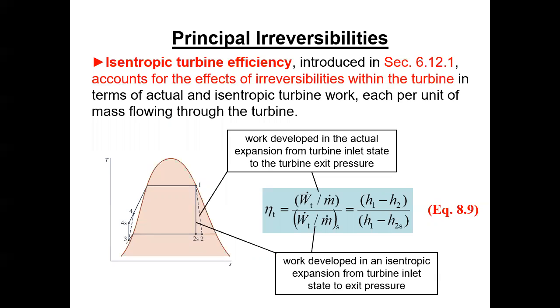That's what typically happens. This isentropic efficiency might be given to you as 70%. So then you calculate the H1 and the H2s, set this expression equal to 0.7, and solve for H2, and that tells you your exit enthalpy. That's kind of the standard problem. Of course, there are always different ways to twist it; these guys writing problems in the back of the book stay up late and get up early trying to find a way to twist this stuff around, but that's kind of the standard problem.